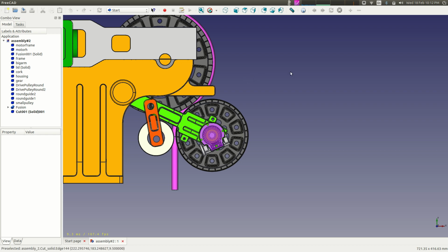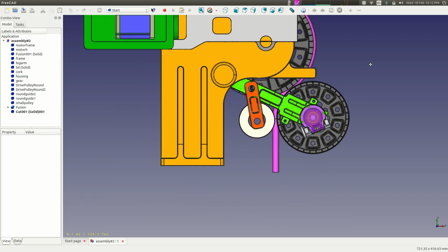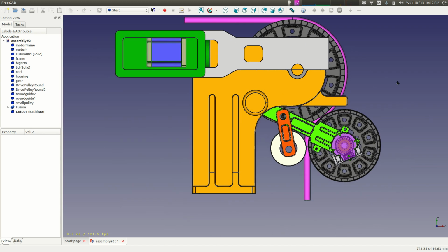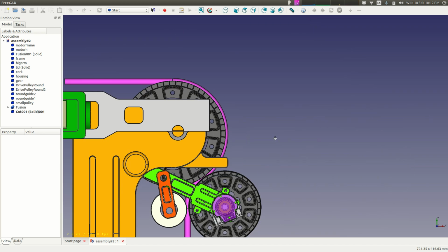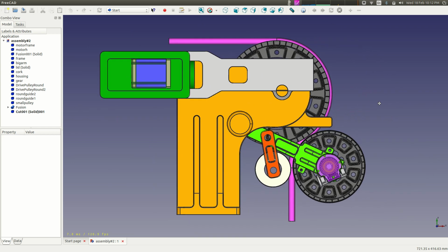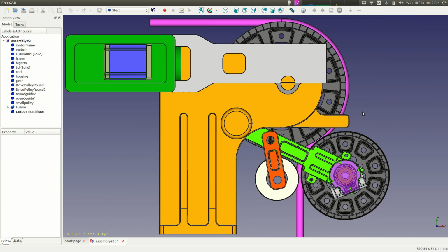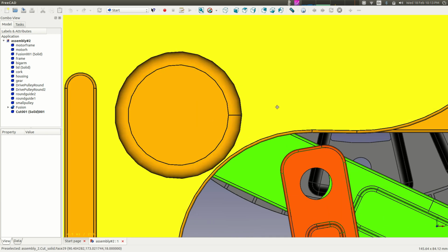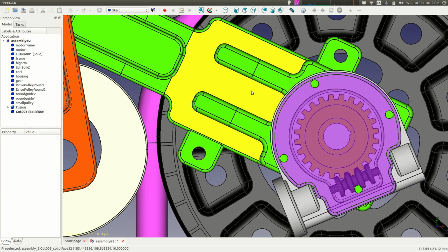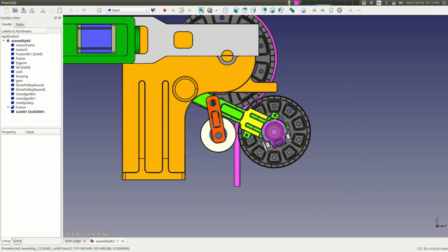So with the regular CAD navigator, clicking and holding the scroll wheel, which is the thing between the two buttons, should bring up that thing there, and that allows you to move the image side to side or up and down without rotating or anything like that. So holding that and moving your mouse around moves it side to side, up and down. Scrolling your scroll wheel just zooms in and out. So if you want to zoom in and then move over down to something that you want, you can do various clicks like that, or scroll back out.